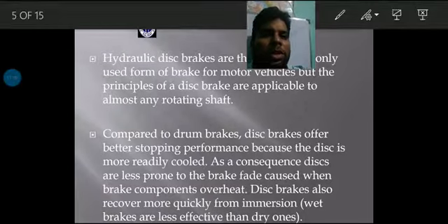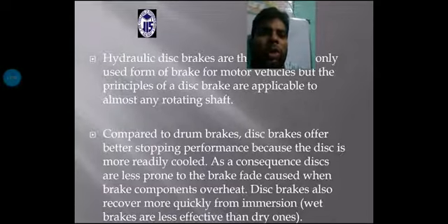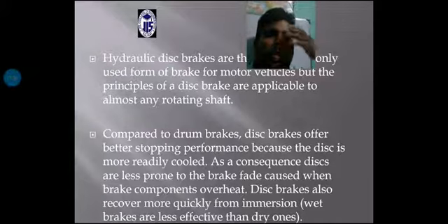Now next, compared to drum brakes, disc brakes offer better stopping performance because the disc is more readily cooled. As a consequence, discs are less prone to the brake fade caused when brake components overheat.